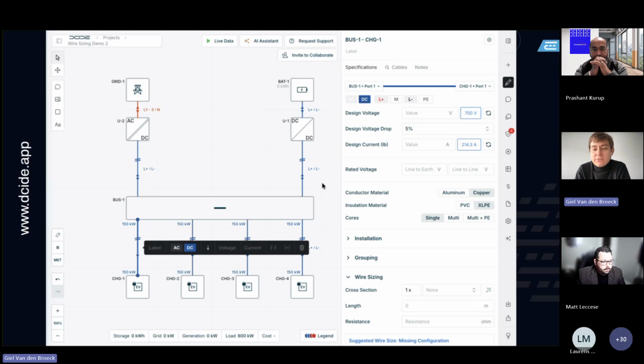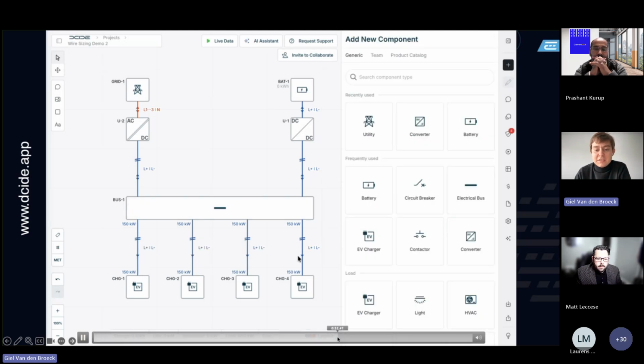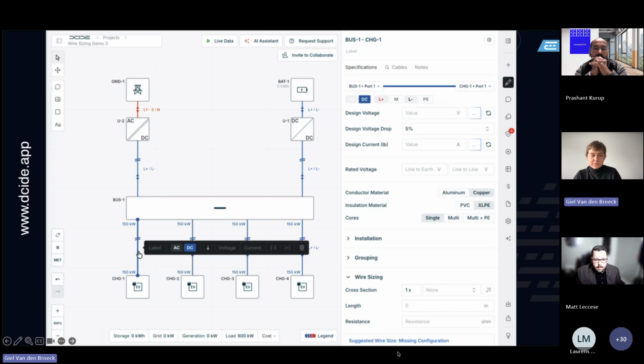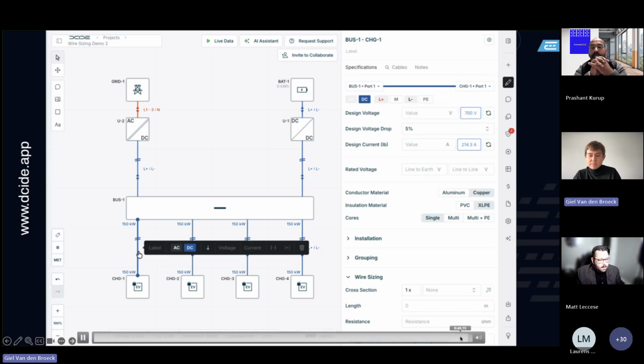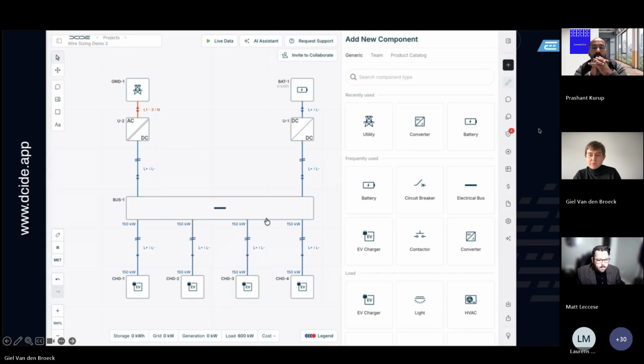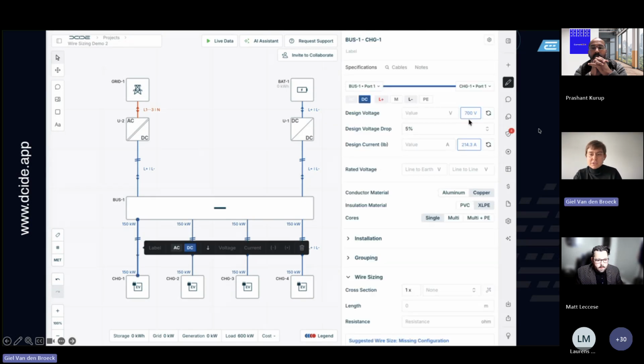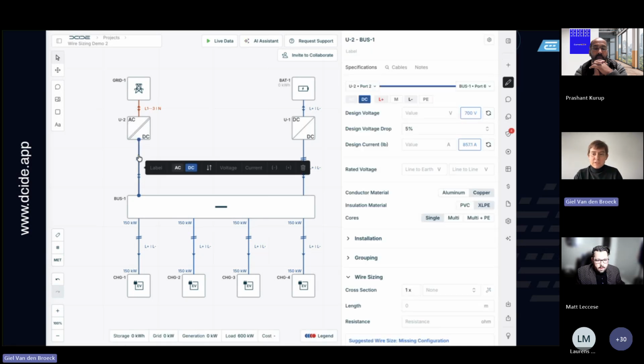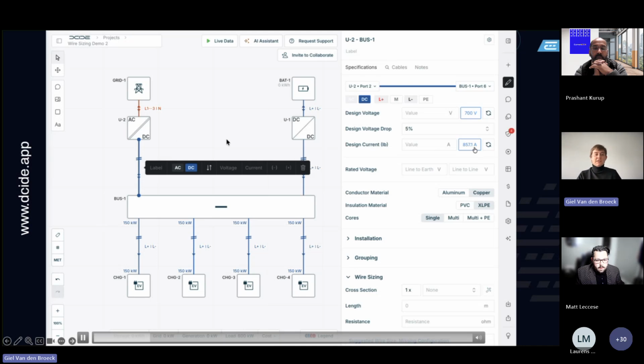So in this case, to meet the 150 kW requirement, it needs to be able to carry 214.3 amps. And then on the battery side, so you see these are all 214. Then on the grid side, if we want to meet the load, it's going to be like 4 times that amount. Let me quickly check. Yes, so on the grid side, you'll see we have 4 times that amount of current.